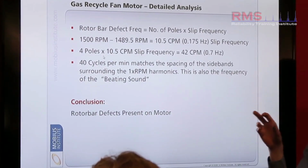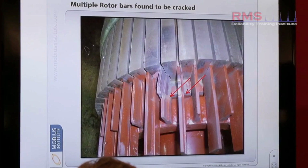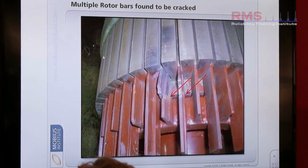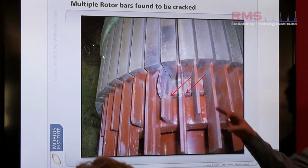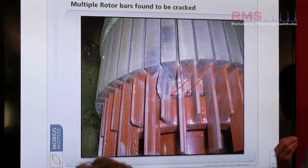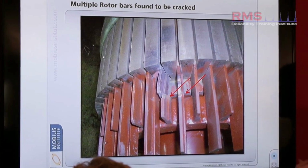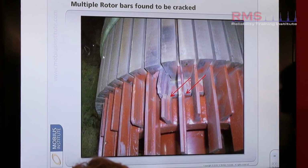And thankfully, the frustration can be we don't always get the feedback, but we got feedback on this from the actual company. They took it on board, they planned the repair, sent it away to the remote repair shop, and that is the damage of the broken bar that caused that distinct particular heartbeat. We knew it wasn't the bearings, we knew it wasn't the fan, we knew it wasn't the coupling, it was down, in this case, to the actual rotor bars.